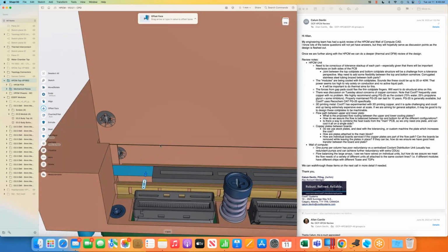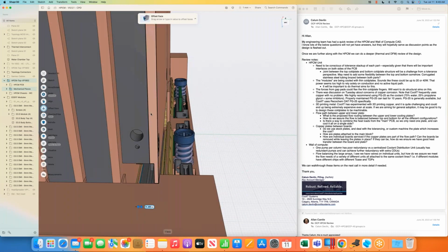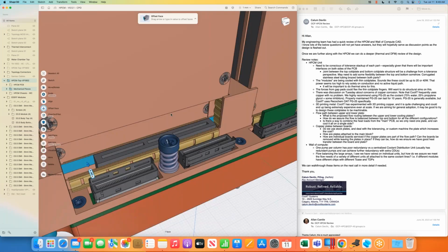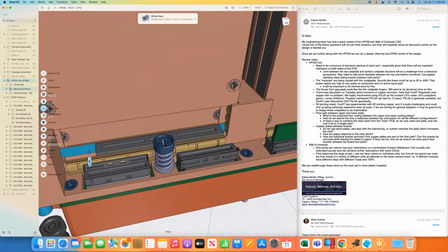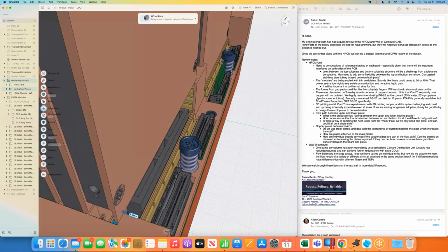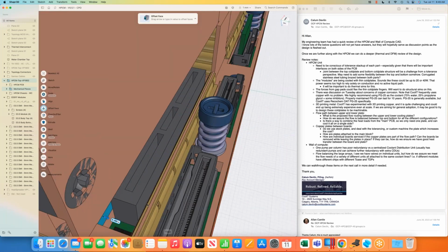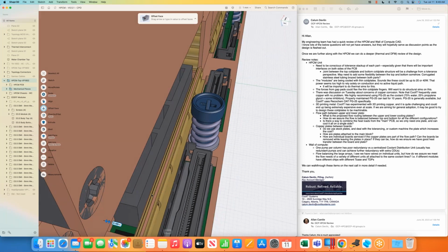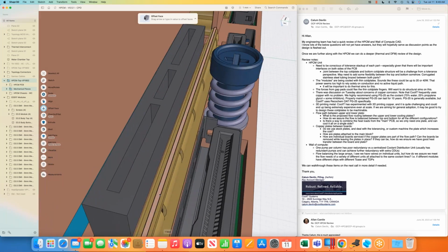So this is one piece of copper that's part of the disk drive or the SSD or the CXL.mem, etc. It slides and mates here. So this is all fixed, and obviously it compresses this. This needs to be a separate spring, like a traditional connector pin. This is made separately and has to be attached to the back plate here, this water-cooled back plate.